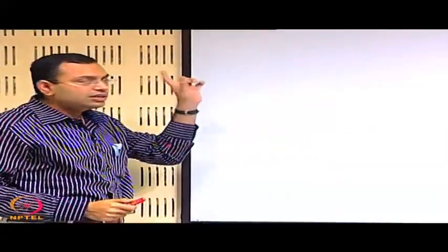So what we have understood is that if you have a solid body in a fluid, the solid body in a fluid may be subjected to different forces, and these forces may come from, one is the skin friction drag which we have identified for flow over a flat plate even without pressure gradient, that is because of the shear, plus there may be a force due to the pressure gradient. So that force due to pressure gradient may give rise to a net effect which may also be a drag force, but to understand what is the net effect, is it just a drag force or something more than that, we have to formally define what are the forces which may act on a body which is immersed in a fluid. So let us do that.